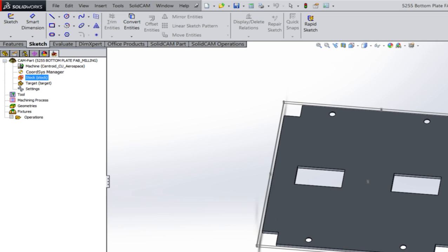So a common technique that we like to use for square parts is we like to put a clamp in from the side here, maybe go in here, and a clamp in from the side here, maybe go in here, and we machine off this side, and that way I won't interfere with these clamps. 1, 2, and I can machine this side and this side. Now it's important that you not put the clamp right there and right there.